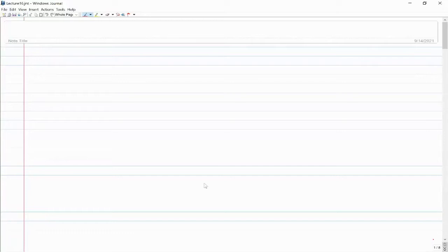Take theta x as unity at all nodes, the constant rotation about the y axis. When there is a rotation about the y axis, the W displacement will be proportional to the x coordinate. For rotation about the positive y axis, the W would be negative, so minus x.